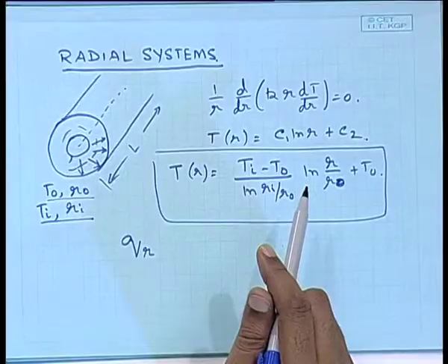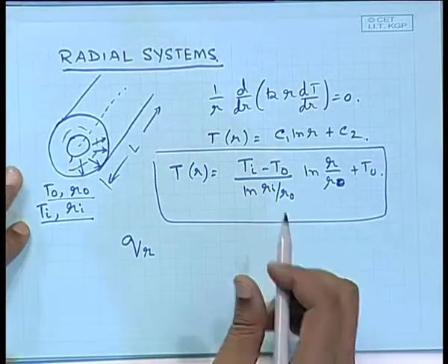The heat rate is going to be a constant, because if you simply apply the conservation one, whatever comes in has to go out. If you have any accumulation or any unbalanced one, then you are going to have a change in temperature, which cannot happen at steady state. So, always keep in mind that in planar systems, both the flux and the rate are constant, whereas in cylindrical or spherical systems, the rate is a constant, but not the flux. Okay. And this would give rise to a very interesting situation, which we will discuss later on. So, the flux will never be a constant.